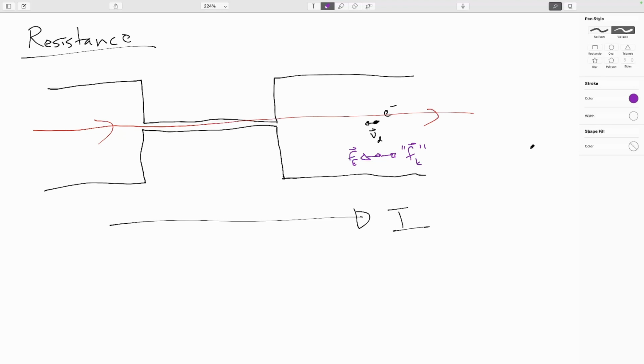In fact, in a typical electric circuit, this isn't very fast at all. The electron will typically be moving less than a millimeter per second. The reason why we see anything happen with our electrical devices is that the electric field sets up very quickly indeed, and then the electric field just interacts with whatever electrons are there.